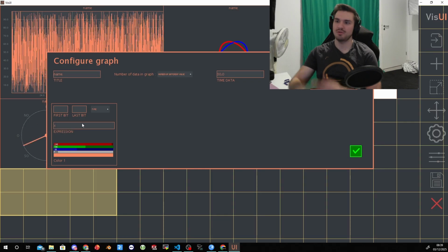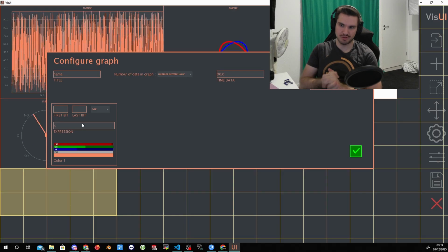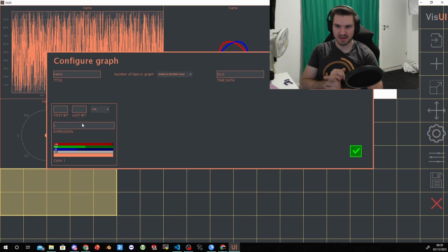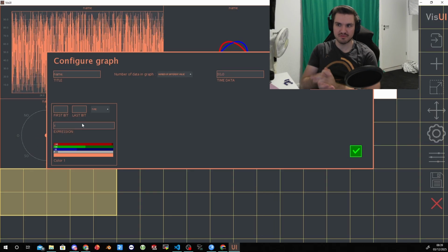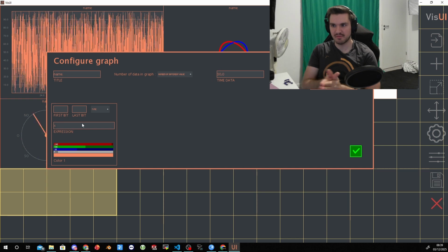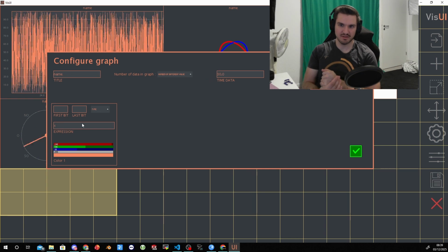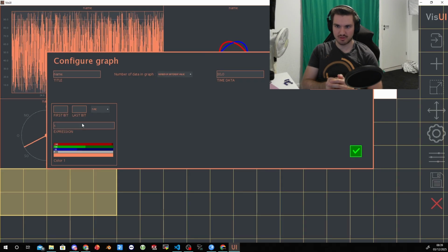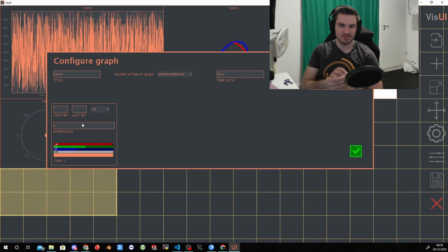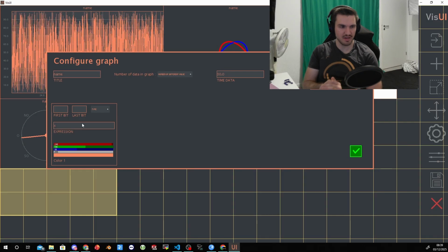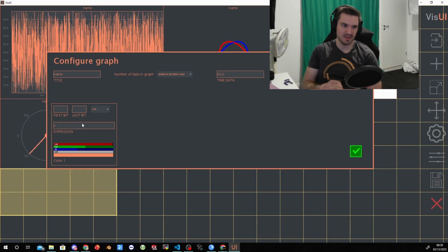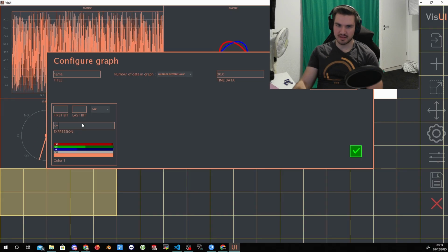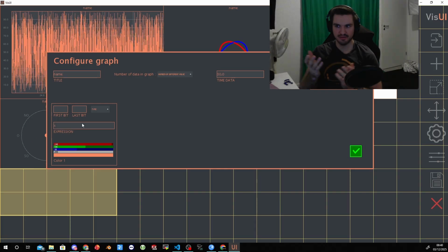Like what we do with pressure, for example: when we have a pressure sensor, we basically remove the 1 bar atmospheric pressure. So we just have a number that is very, very small because the pressure is not moving that much. And this is easier to transmit by telemetry because you can have more precision and send a smaller number of bytes. You can use an unsigned integer of 1 or 2 bytes and it will be fine. You will have plenty of precision using it. But when you use this, you can basically have the expression of pressure and do the calculation to get the height of the rocket.